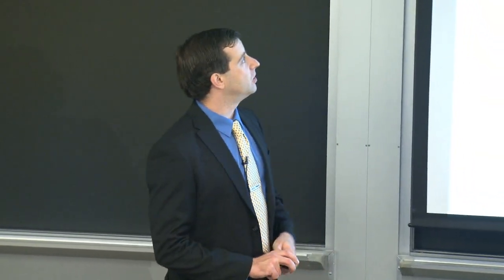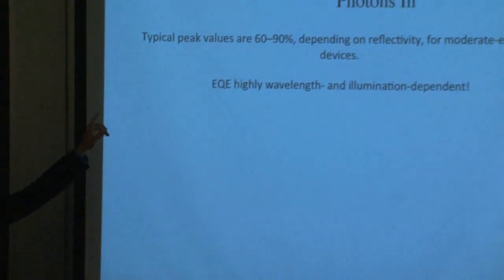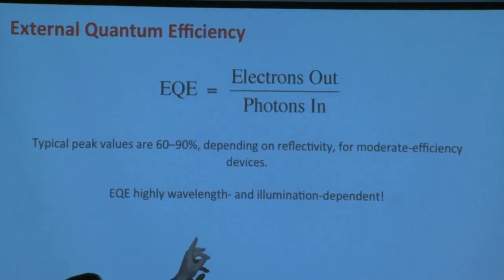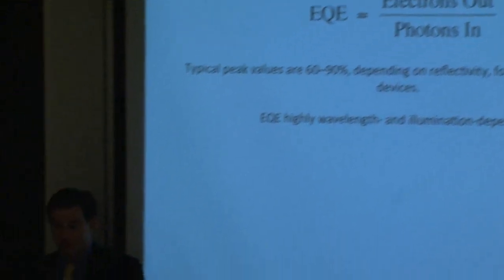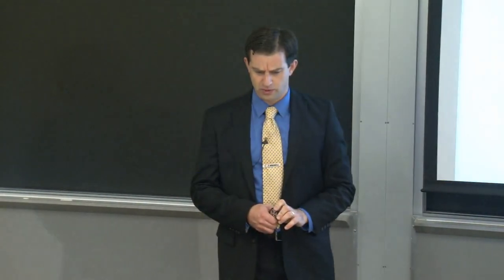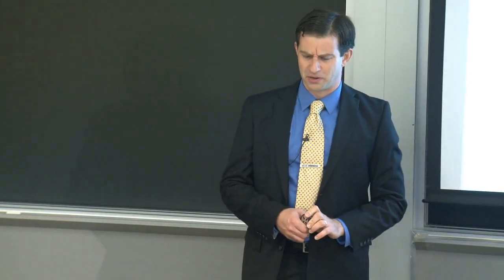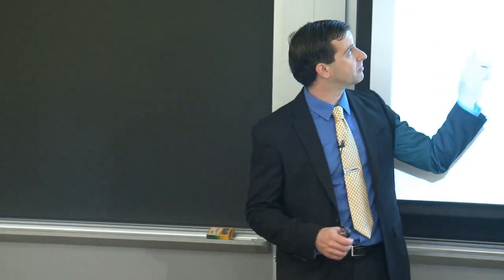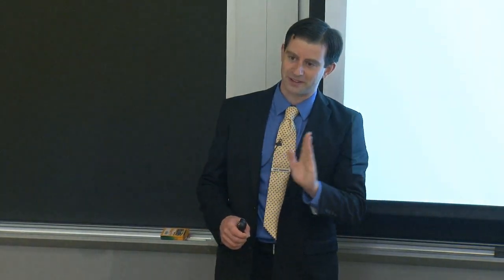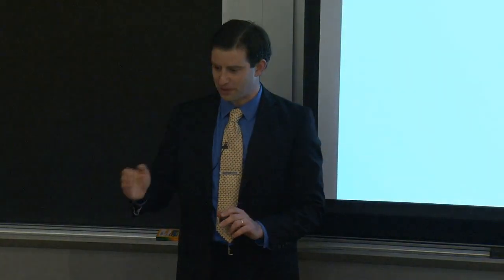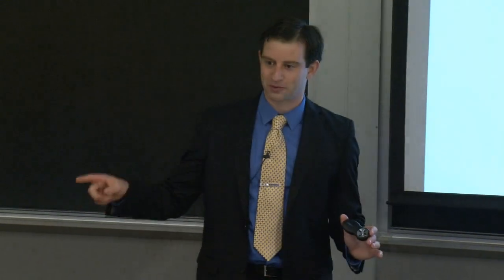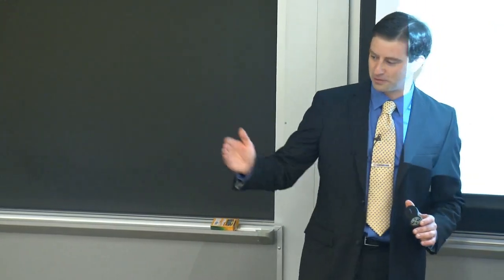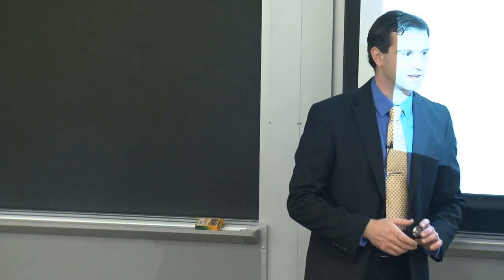In principle, EQE should have EQE as a function of lambda, really. And the photon in is going to be obviously at a certain wavelength, usually. I've rarely heard EQE given in a polychromatic sense, where they take an entire solar spectrum and measure the quantum efficiency average. Usually, quantum efficiency is measured wavelength by wavelength. And so you might change your monochromator settings 20 or 30 times over, or even more, over a quantum efficiency measurement to really map out the entire solar spectrum, from short wavelength in the ultraviolet all the way to longer wavelength in the infrared. And you're absolutely right.